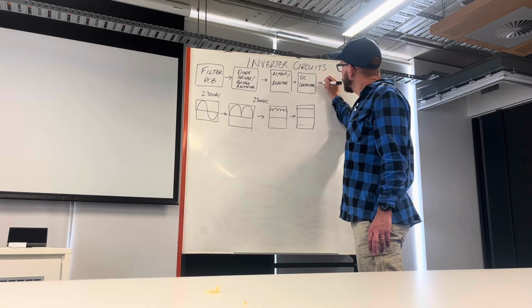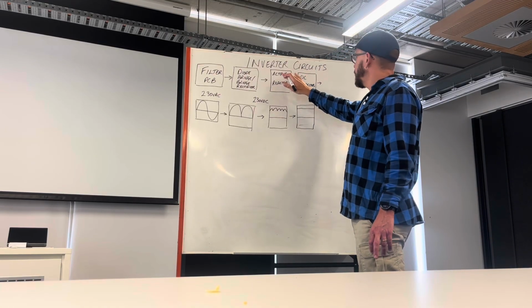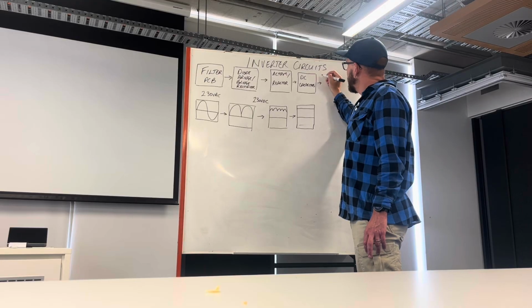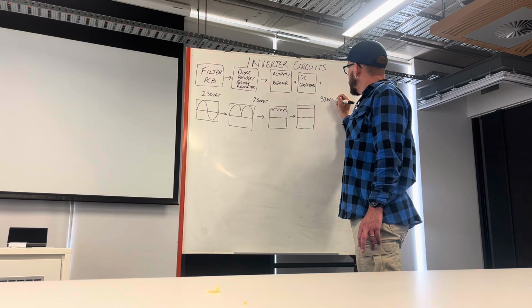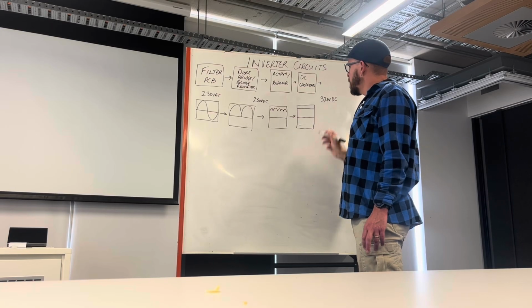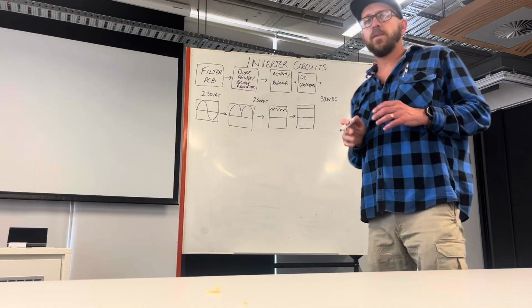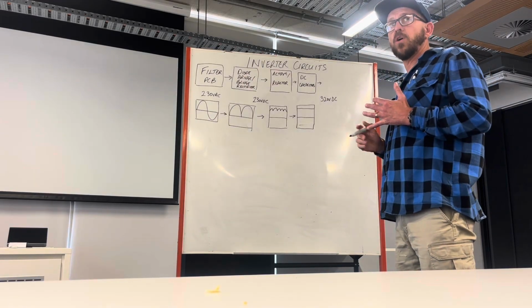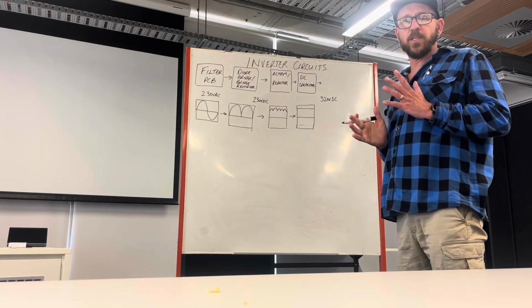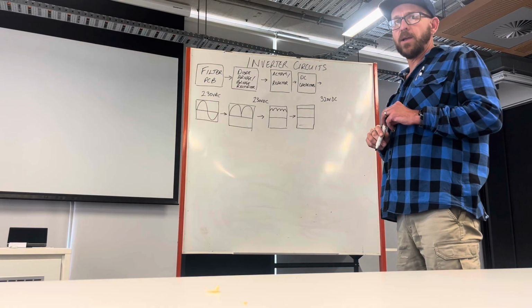Typically, by the time we've gone through the power factor correction equipment and the capacitors, we're sitting around 320 volts DC, nice steady voltage. And once we've got that 320 volts, it's ready to be used for things like DC voltage back to the control board, but it's ready to be switched by the inverter board to drive our compressor.